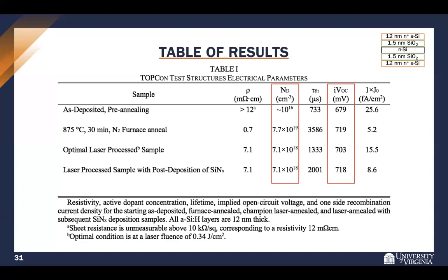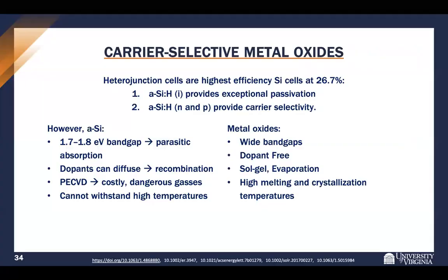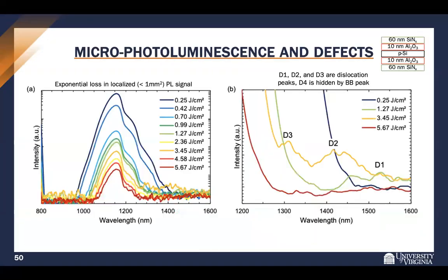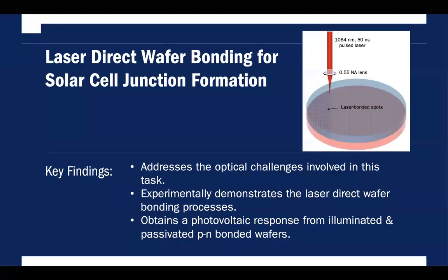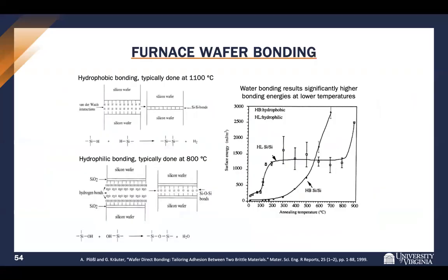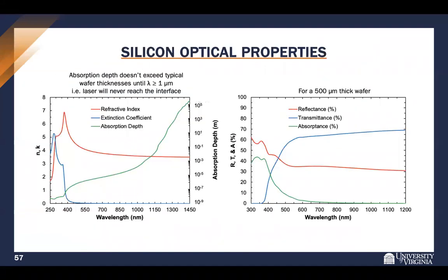Another question I had was, when you do wafer bonding, ideally it would be nice if you could have localized heating right at the interface between the two wafers, right? Mm-hmm. And so instead of heating the top layer, I'm trying to understand the rationale behind the wavelength you selected, and you showed as a function of depth what the absorption might be. I guess you selected the wavelength right at the onset of the absorption of silicon, so that you have absorption somewhat deeper, beyond the first wafer. Was that the rationale? Right.